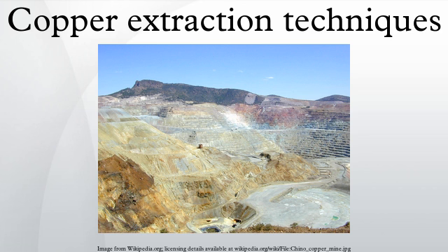The furnace is fired with burners using pulverized coal, fuel oil or natural gas, and the solid charge is melted. Reverberatory furnaces can additionally be fed with molten slag from the later converting stage to recover the contained copper and other materials with a high copper content. Because the reverberatory furnace bath is quiescent, very little oxidation of the feed occurs. It is essentially a melting process.